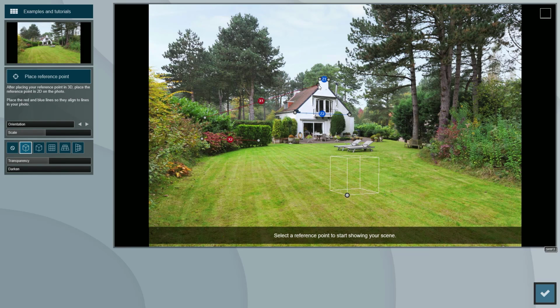If you're using a different photo, which doesn't contain a house like the one we're using here, make sure you align your lines with objects in the photo that, in reality, are 90-degree, 4-sided objects that are parallel to the ground. Some examples of this would be 2 perpendicular walls, a swimming pool, or a table. After placing these lines, Lumion can derive the point from which the photo was taken. This is needed to get the same perspective for your 3D model in Lumion. When adjusting these points, you can hold Shift to slow down the adjustment and precisely set the position.